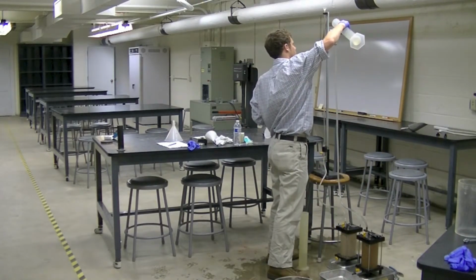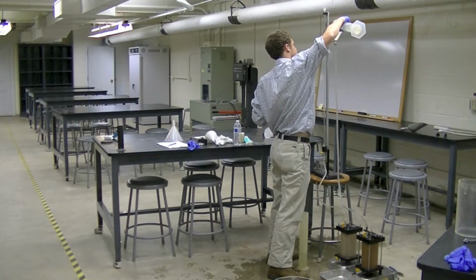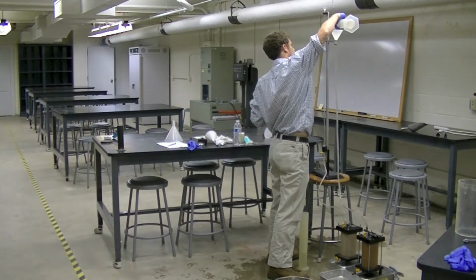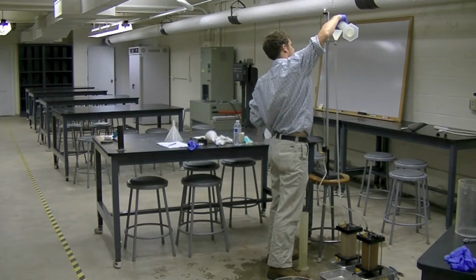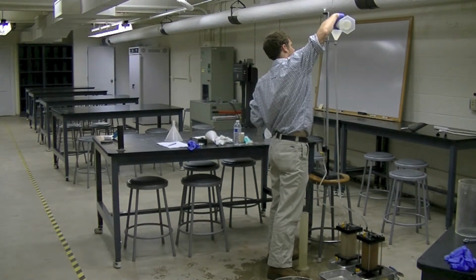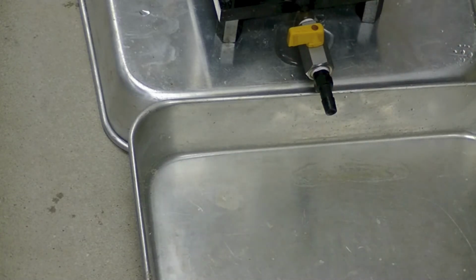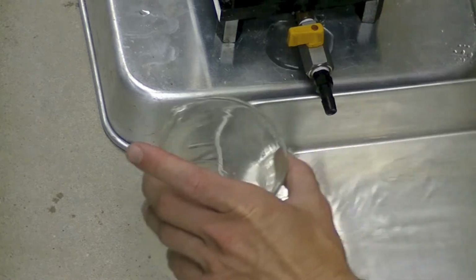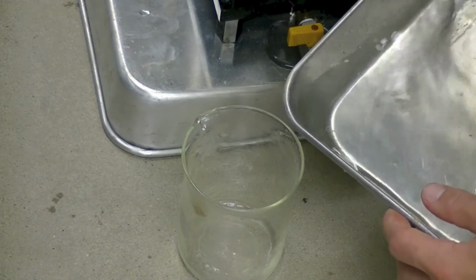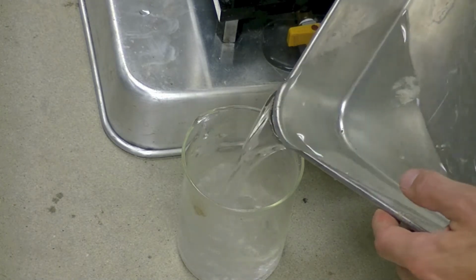While starting a timer, quickly open the outlet and allow water to flow out. During the specified duration of time, 30 seconds in our case, keep the hydraulic head constant by adding water to the funnel. After the time interval has passed, immediately stop the flow, record the exact time interval, transfer the liquid from the pan into a beaker or column to obtain a more accurate volume reading. Record the volume in units of milliliters.